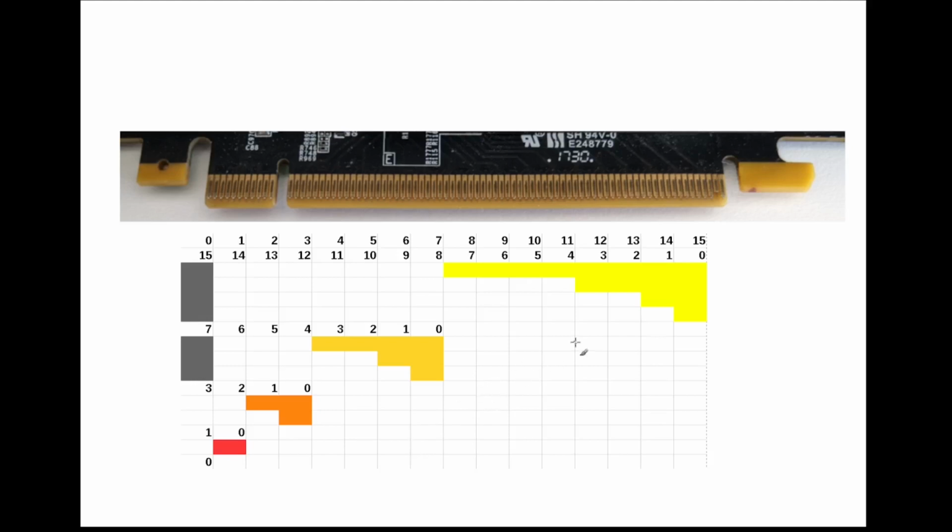It is possible in this case for repair to rewire either lane 15, 7, 3, or even 1 to the first lane, which is why you will see some guides also suggesting to simply rewire or change these 2 lanes around. For cryptocurrency mining, rewiring a single lane is usually sufficient to restore full performance to a graphics card, so doing more than 1 lane is usually not necessary. However, games require more bandwidth, and rerouting in GPU traces also poses the risk of signal integrity issues, even if the card was somehow able to work.